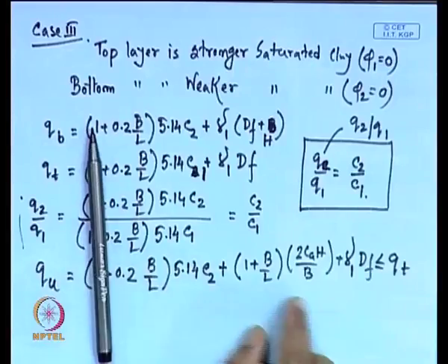Once we get the Ca, then in the final expression that Ca term is required. So, we put the Ca value there and calculate the ultimate load carrying capacity of the soil, because all the other terms, the thickness, dimensions and properties, are known. The only main unknowns are Ks and Ca, and those two we can determine by using these charts. So, in different cases we have to judge where we will use the first chart and where we will use the second chart.